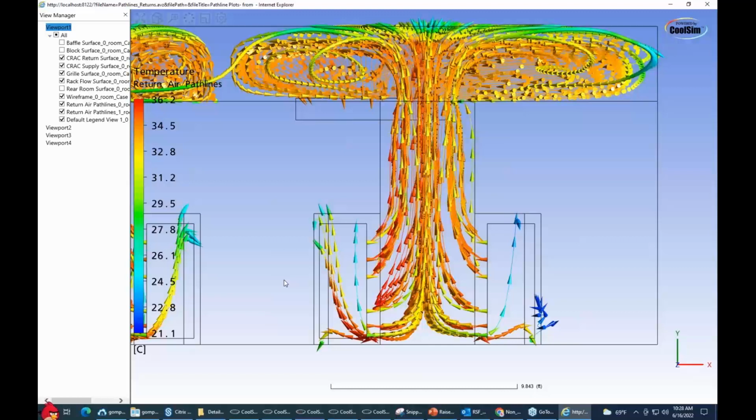If these racks are too close together, this will cause a high pressure region. These designs tend to be, the white space is expensive. So I want to put as much of this IT equipment as possible in there. And trying to stack it too closely together will cause some issues that aren't necessarily obvious to the casual observer.